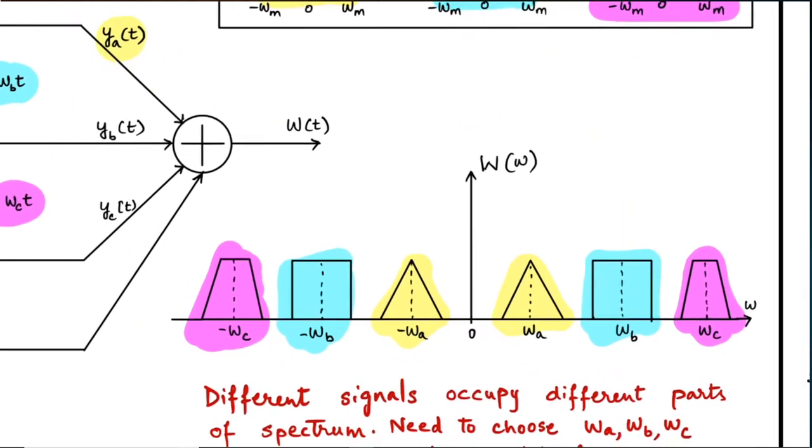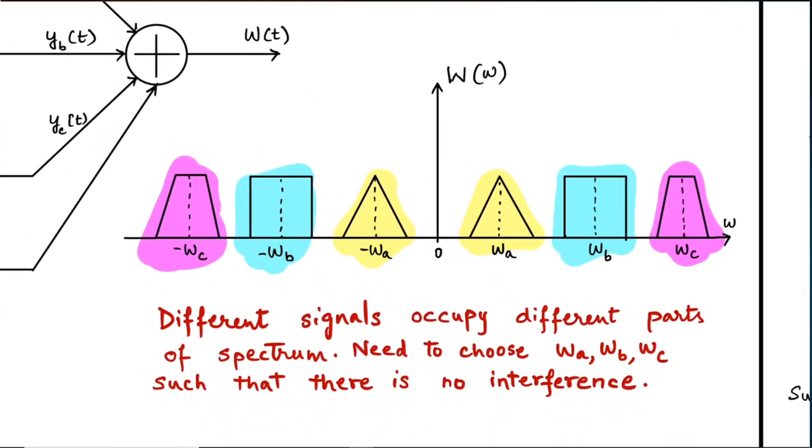And there are other aspects of this we could discuss as well, which is, can this be closer together? Yes, they can be very close to each other. The problem with that is then they will start interfering with each other. There could be crosstalk. And also there could be problems in designing filters that are extremely selective and only pick out one triangle or one rectangle. So yes, you can bring them close together, but a guard band between them is good insurance policy in order for the filters to not be burdened with the selectivity.